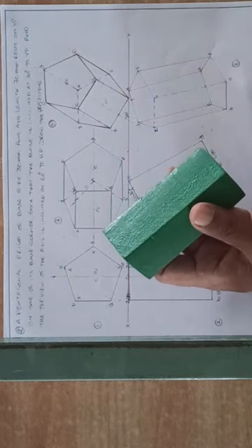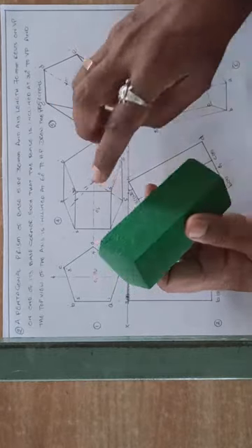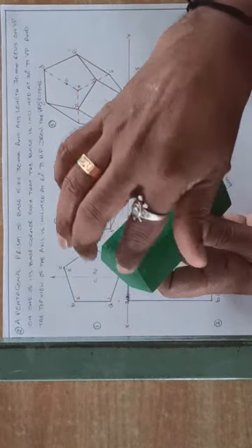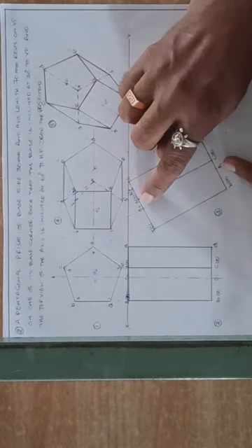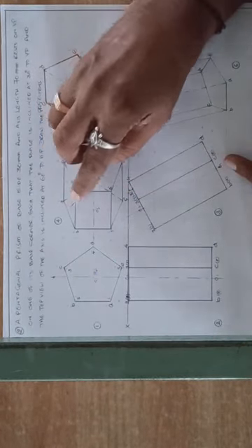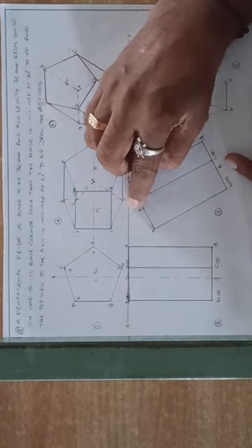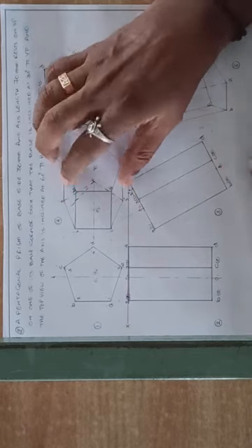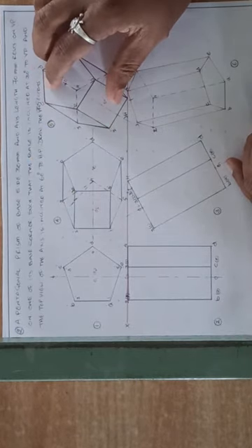In this position, you can see this face. So make this face visible, thick, and this face only half is visible, and this side, which is 4, 3 and 4, 5, is not visible. Make those two edges hidden lines. So like this.